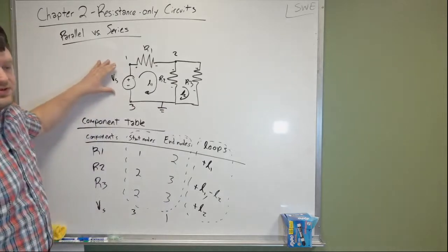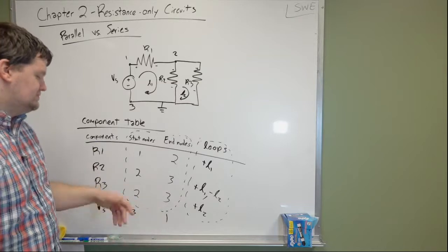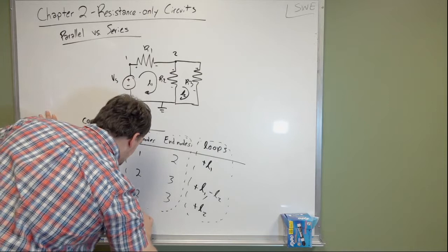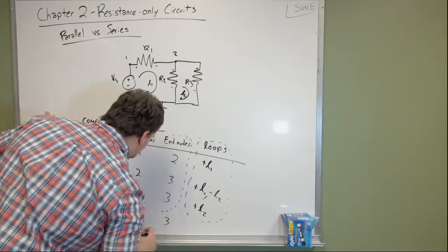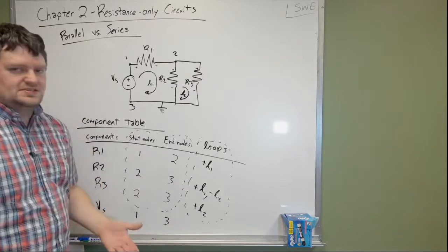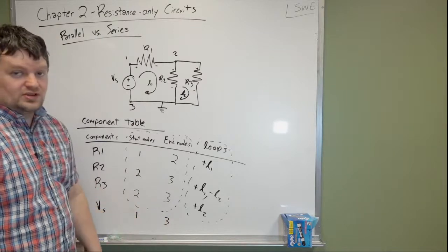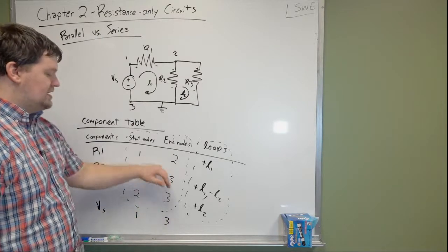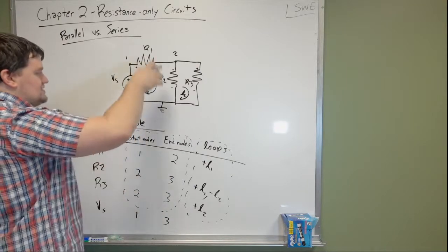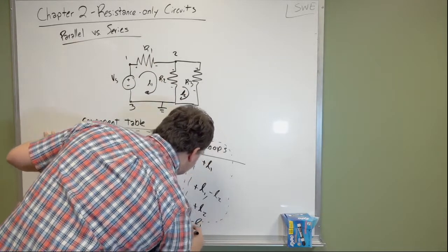Because it's a source voltage, we're just going to go ahead and flip that. Otherwise, I guess we could write it backwards. I hate doing that, but here's the positive end, here's the negative end. We just have to remember that since this is a source voltage, it's forcing current to flow from the negative end to the positive end, whereas all of these being passive have current flowing from the positive end to the negative end. And here, this is also negative in loop 1.